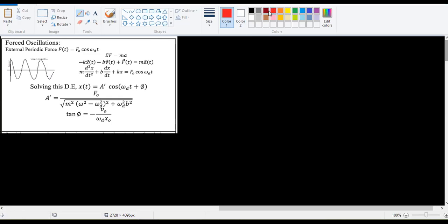You see, the spring force and the damping force are the same. Only thing, now you are standing behind the swing and you are pushing the swing, which means that is your extra force, positive force. So these things are opposing the swing action, and this is adding to the swing action. You are giving it in the positive direction. So that's why this is minus against it, and this is positive. Again, most important formula in mechanics is sigma F is equal to ma.